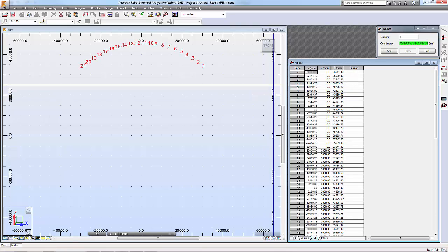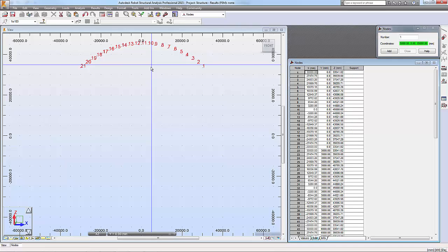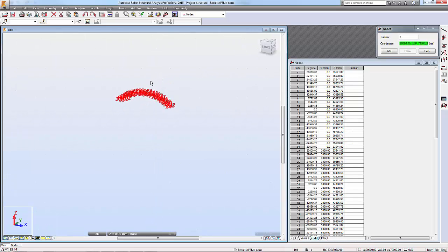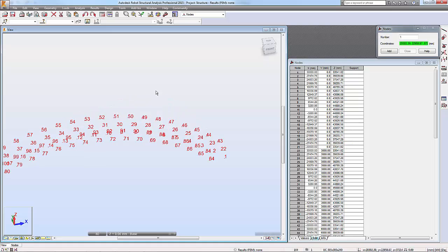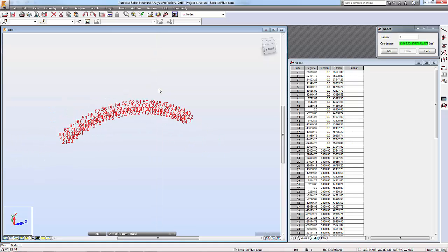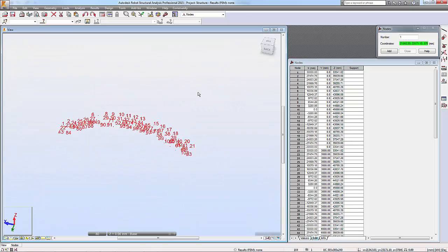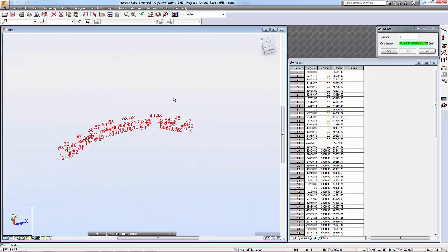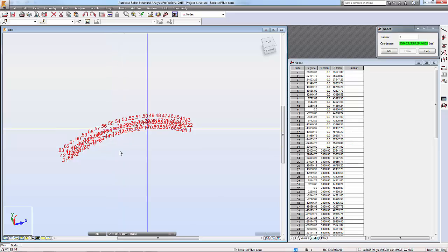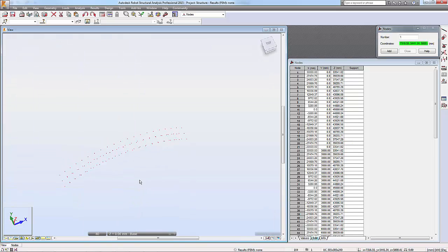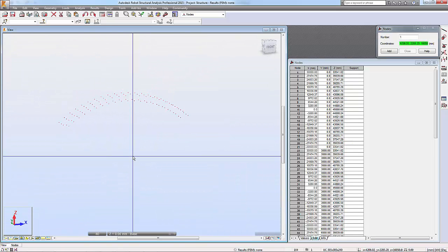So you see, once you paste this, the truss nodes have been generated in here already. You should be able to zoom in by holding the shift key and the middle scroll button of your mouse, holding both, and then you can spin the structure to have a look. Possibly the numbers here are not good to view in these structures. You can disable them by clicking on this one. So you see that's the structure, that's the nodes we have created.